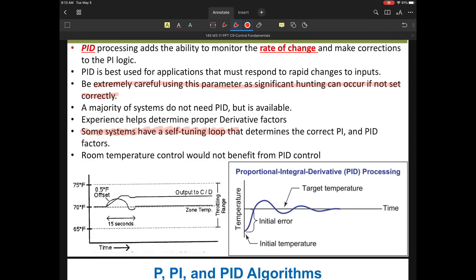In an economizer loop, you're driving a control valve, an actuator, fully open or fully closed, and because the outside air temperature will change so much, it's not as simple as that. You're going to see a different change in the variable when it's colder outside versus when it's a little warmer outside. So it doesn't always work perfectly, but it is still a function.